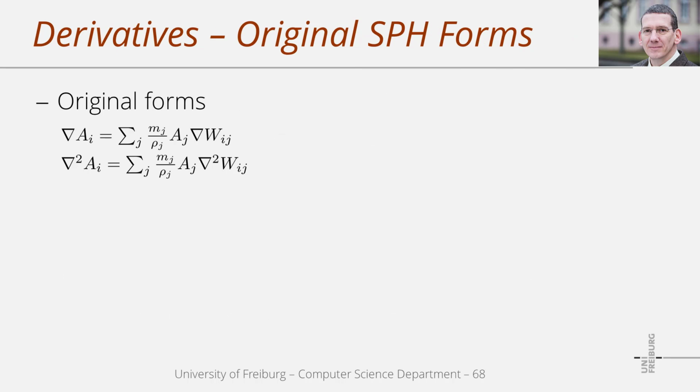In terms of the concept behind SPH, namely the reconstruction of functions and derivatives from discrete samples, there exist standard SPH expressions for the derivatives. We know that we would like to realize the convolution of the samples with a kernel function or with a derivative of this kernel function, and we can approximate this convolution at a sample i with the stated sums over nearby samples j.